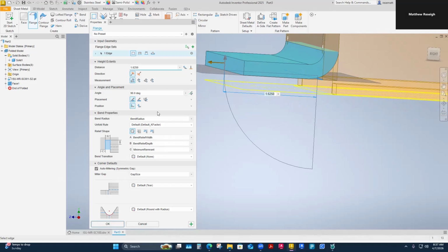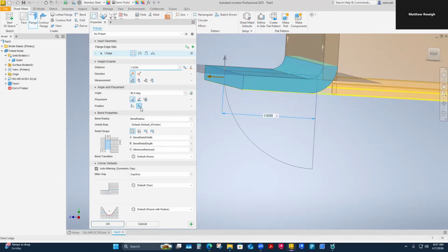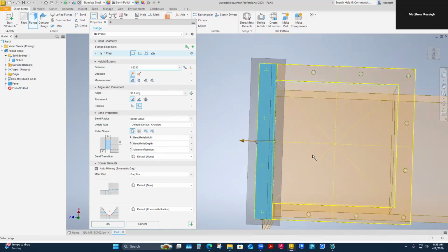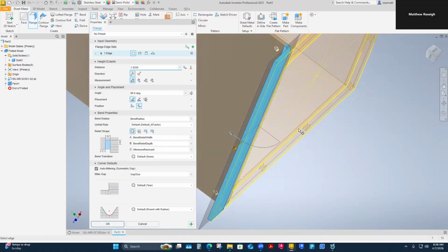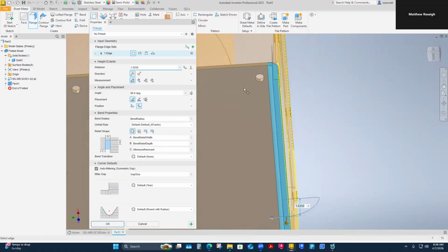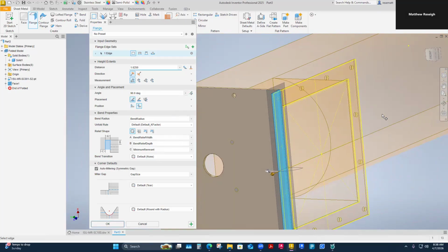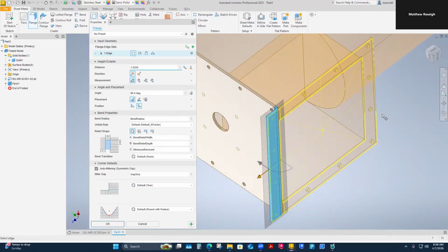So I feel like the one that does that is the position here. I'm not changing anything as I move down through here, just the measurements or the placement. I'm just going to change bend position here like this and push it down. Now I can see that I'll be on my three-sided part. This will be the fourth side, and they will lie on the same plane or surface so that I can bolt up a mating flange to it to bolt on the discharge chute, which is really a squared around.